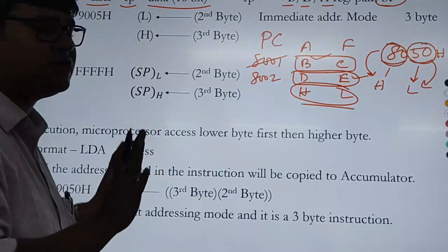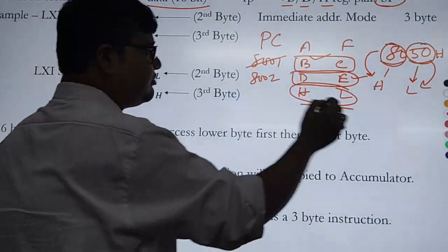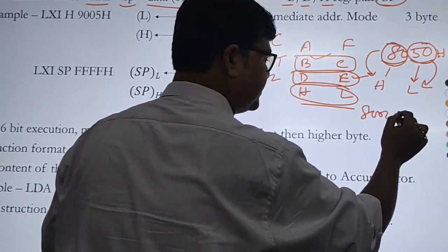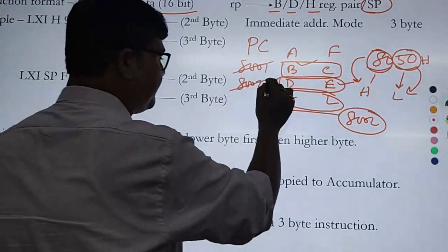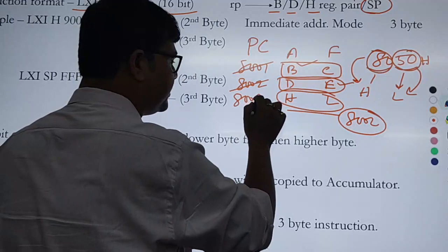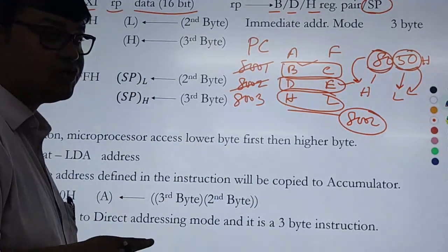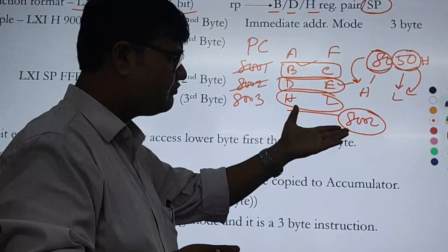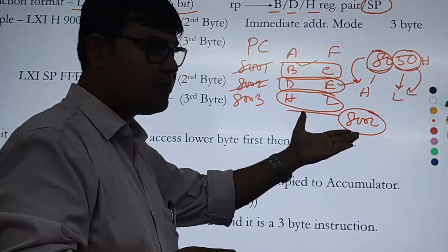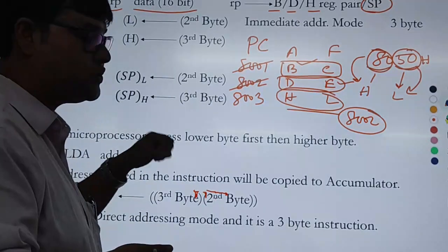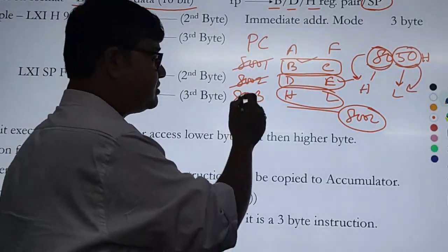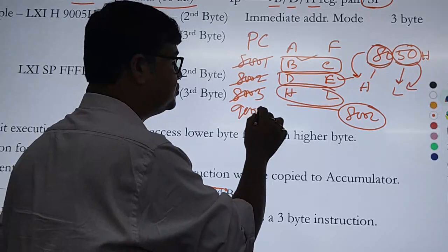So if we are going to break this common execution process, it is very simple. We are going to change the value of the program counter. Say now 8001 is being accessed. For example, the microprocessor is going to execute 8002, so automatically the value in the program counter becomes 8003. But now I want that after the execution of 8002, the microprocessor should go to 9002. So by default or forcefully by instructions, we change the value of the program counter to 9002.